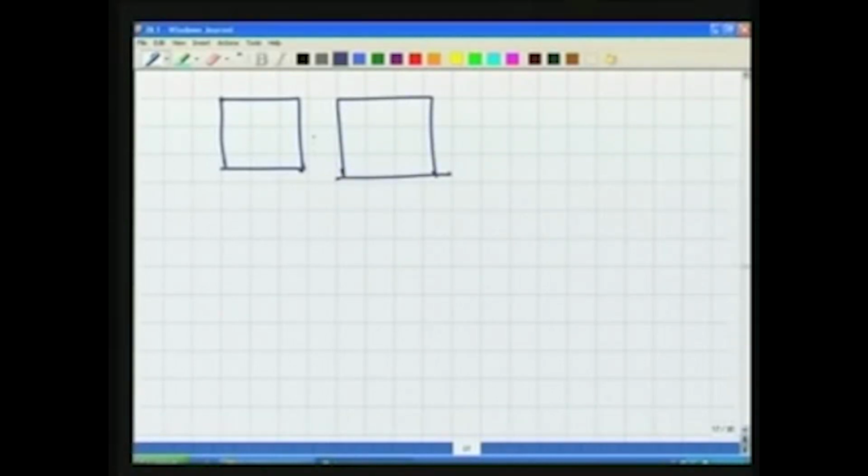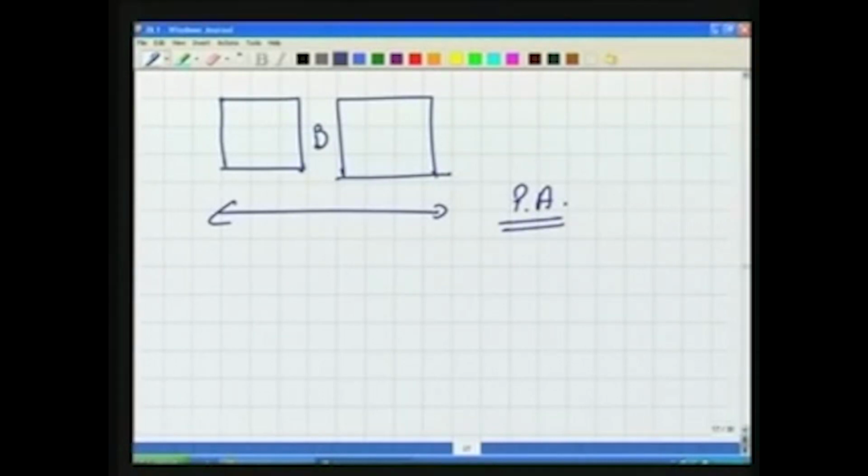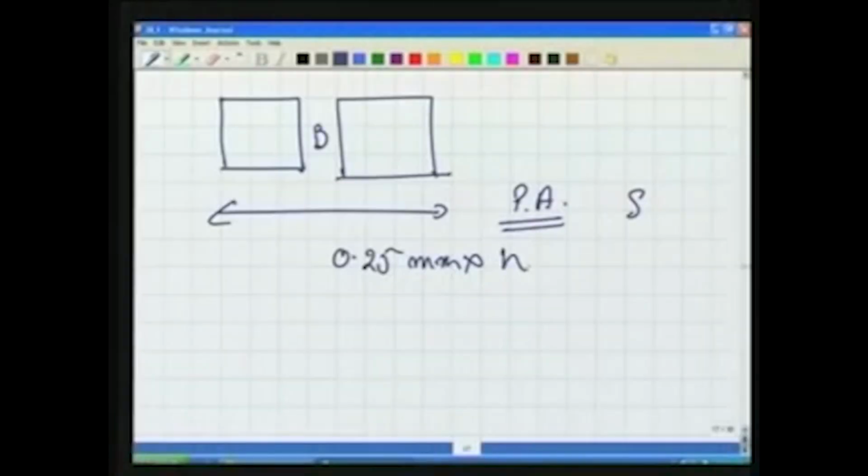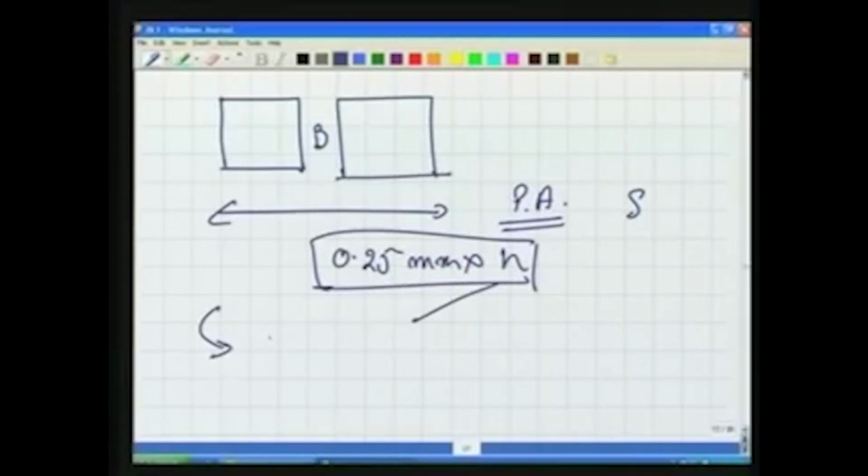Should we measure very accurately in the ground, as in the previous example? Should we measure these two objects, where that distance was B, as separate objects there in the ground, or should we measure them as one? Well, the decision is to be taken by your plotting accuracy: what your plotting accuracy is, what your scale is, because you compute the plotting accuracy multiplied by your scale, and any distance, any object, any separation there in the ground which is less than this value should not be measured, because we are not able to plot it. We are able to plot only the things which are more than this. So, this is very important. We should always keep in our mind that what information we should measure in the field is controlled by the scale.